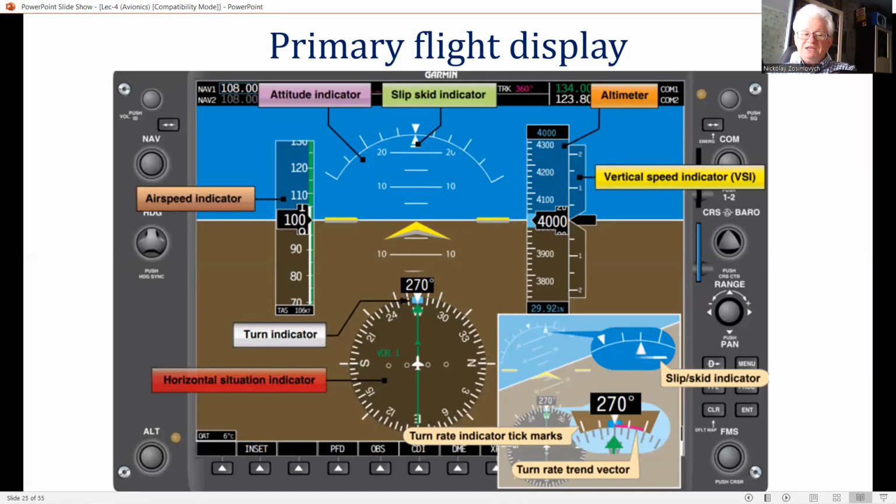It should be noted that the attitude director indicator is the key display on any aircraft for recovering from unusual attitudes, particularly when the normal outside world visual cues are not present, like flying in clouds or at night. A pilot can become disoriented. The normal display of attitude on the HUD is not suitable for this purpose, being to a fine scale which consequently moves too rapidly.